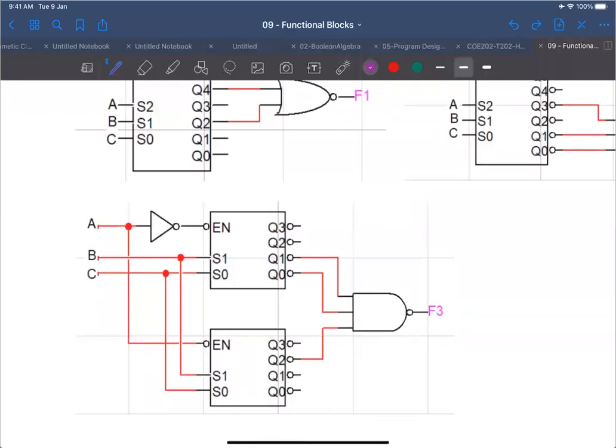They're bubbled twice, so I'm guessing 1, 0, and 2. Yeah, so here when you have a bubble at the enable, that means it is enabled when it is 0. But there is an inverter, so. Yes, but there's also an inverter before. So it's just cancelled out.